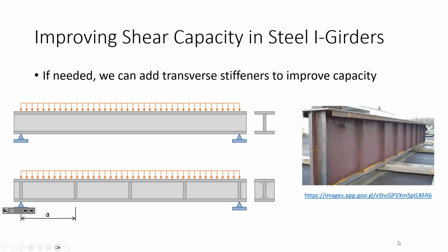The process by which you place those stiffeners is somewhat similar to how you lay out stirrups in a reinforced concrete beam. The math is different, the mechanics are obviously different, but the process has some similarities. For those of you that take reinforced concrete design, you'll find that for a simply supported concrete beam, you'll space your stirrups pretty closely together at the supports. Out in the middle, they get spaced somewhat far apart. The reason is that the shear diagram is pretty low out here in the middle. Near the supports, they're spaced pretty close together, because you have a lot of shear out there.